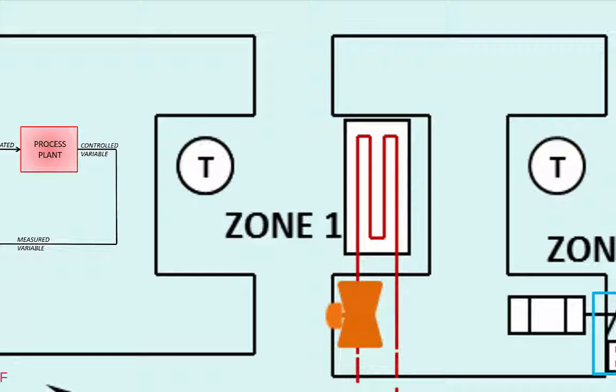There would be a thermostat located somewhere in the space which controls the position of such a valve. Again, the term thermostat means that both the temperature sensor and associated controller are just housed together. In this case, the set point for the controller would just be the temperature you want your space to be at. The control variable would be the room temperature. The control device would be the two-way control valve, and the process plant would be the radiator.